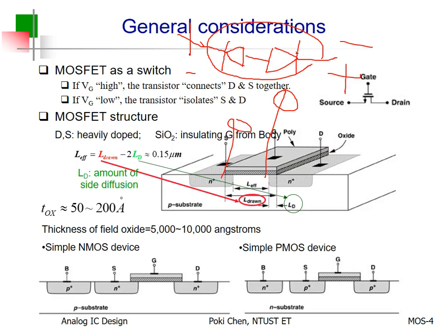If you want to stop it, you need to apply some kind of very strong voltage to turn them off. So for operation speed, depletion type is much better than enhancement type. But for power consumption, depletion type is too much. So usually we don't select the best. No. We select the least power.